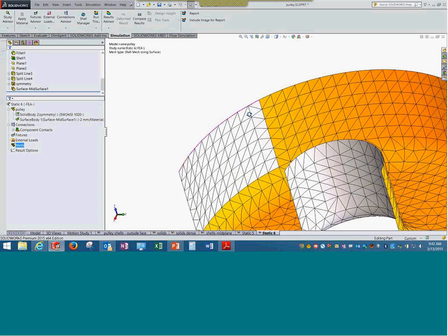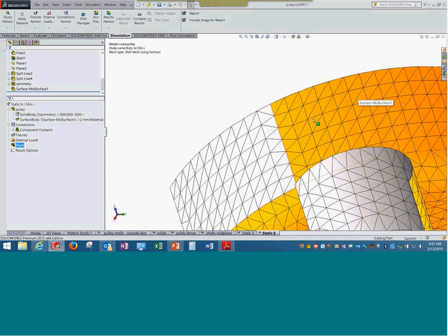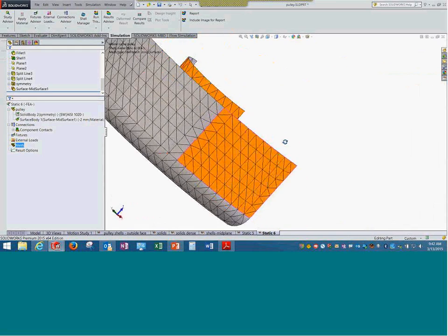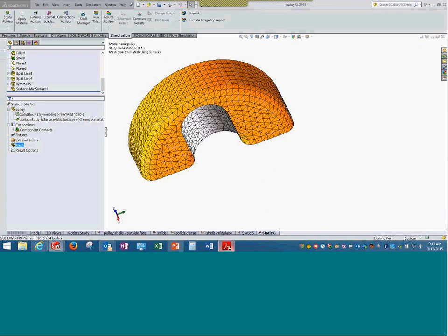Other than this, if you see such a thing, stresses will be incorrect. Normal directions are very important for shell elements in huge geometries. By the way, by default now, the shell meshing solver has capabilities by which it can actually ensure connectivity or smooth creation of elements. However, if the solver has failed, then you can do it manually. This is the way.